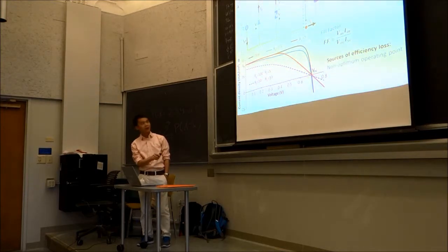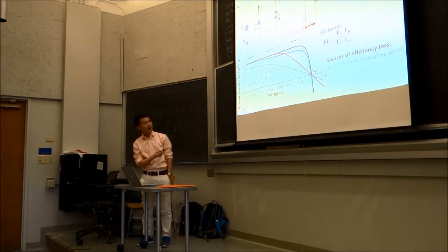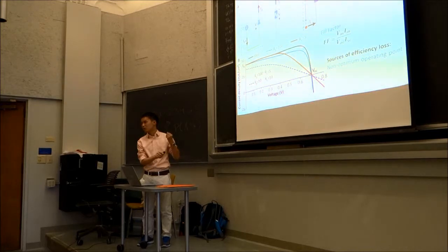And this black line is the ideal case. Let's focus on this one. You see the ideal IV curve is very similar to a kind of square box. And how close this is to a square box is called the fill factor, where you can pick one point along this line that gives you the maximum power. I hope you remember that power equals voltage multiplied by current, right? So along this line, there is one point that gives you the maximum power.